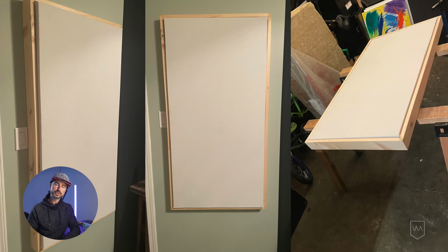And a lot of people see studios with those little 2-foot by 4-foot wall-mounted panels. And those just are not going to provide the amount of low frequency control. They'll be great for mid and high frequencies that are more easy to control. However, in this room, I already know low frequencies are going to be the biggest challenge in the room. And so area of coverage matters.